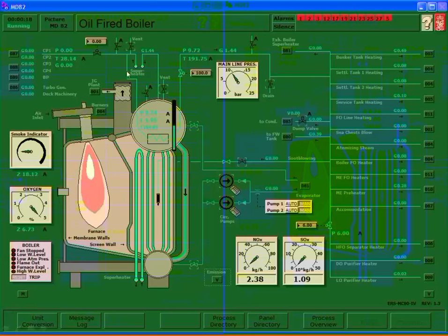Then from the superheater, it's going to go down and into your desuperheater, come out, and through your desuperheated steam stop. Now, the other thing on this too, if I'm ever to ask you what is the purpose of a desuperheater, there's only one answer I accept, because that's really what it's there for. It does some other things, but that's why it's there, and that's only why it's there, is to protect the superheater by ensuring all steam flow is through the superheater.